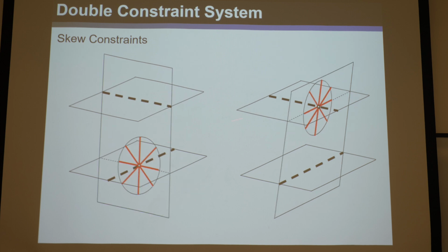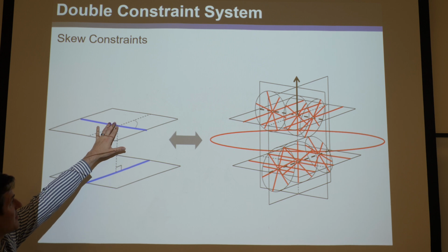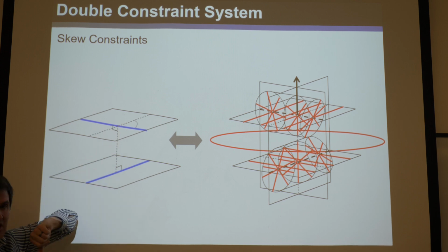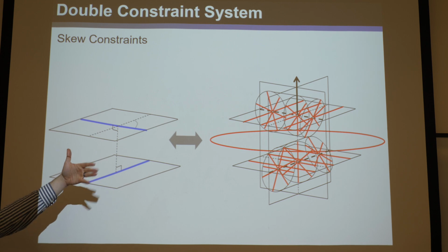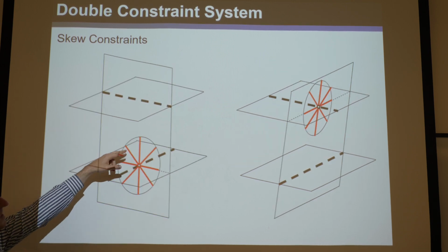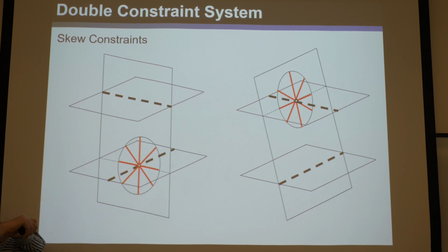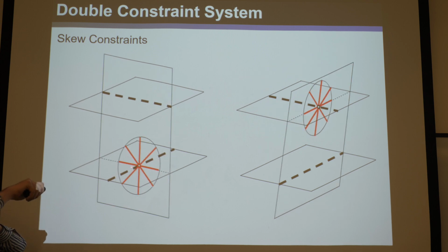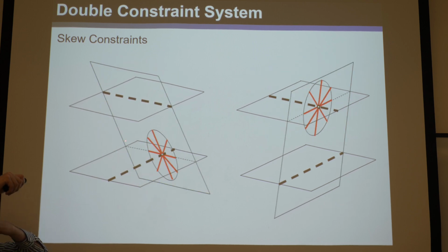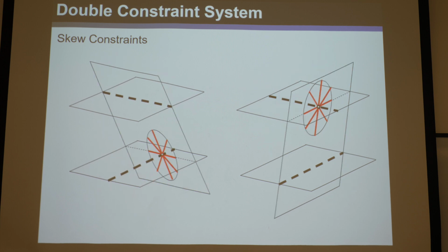that this would be the freedom space, something like this. It's easiest to visualize when this is 90-degree skew, then these dashed lines are 90 degrees from each other and it's all nice and clean. But you could imagine this image would still work if the skew angle was cocked to something not 90 degrees. You could still hinge about it and sweep a disk on the plane, hinging about it through this line. And they'd be just kind of cockeyed. But it would still be the same freedom space, right?